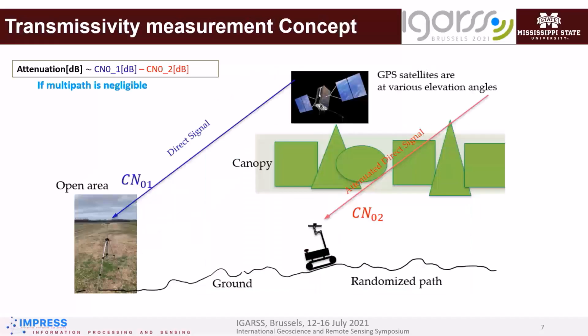In this experiment, we investigated the feasibility of using the inbuilt global navigation satellite system (GNSS) chipset within an Android smartphone and a custom GPS receiver to map relative canopy transmissivity using an unmanned ground vehicle. The experiment setup involves a UGV equipped with a smartphone or a custom receiver on top of a stabilizing gimbal under the tree canopies that receives the attenuated direct signal, and a separate phone or custom receiver placed on a tripod that provides a reference signal in an open area.